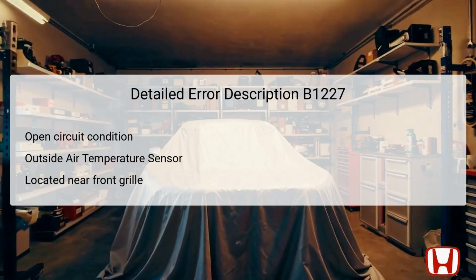The DTC B1227 signifies an open circuit condition specifically affecting the outside air temperature sensor. This sensor plays a pivotal role in the vehicle's climate control system by detecting external air temperature, which helps regulate heating and cooling. Its location is generally near the front grille, allowing it to obtain accurate readings of the outside atmosphere. The sensor sends signals to the climate control unit, which then adjusts the cabin temperature accordingly.